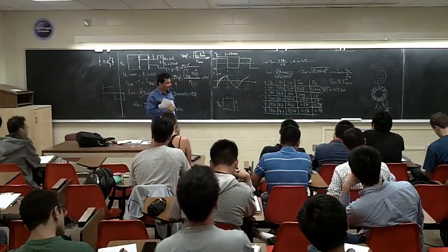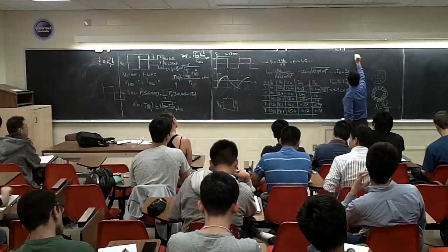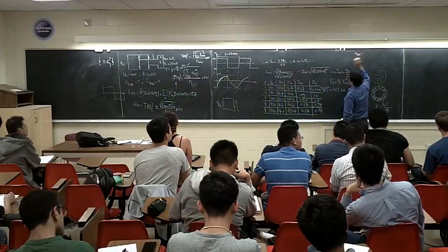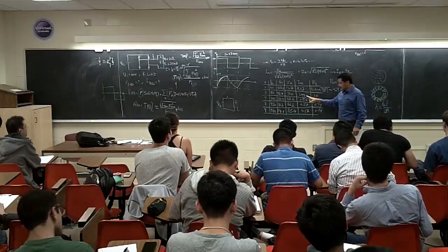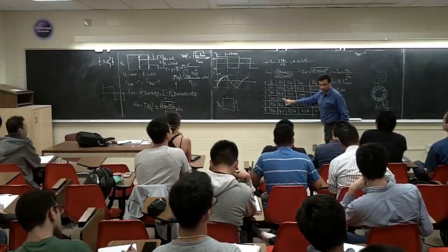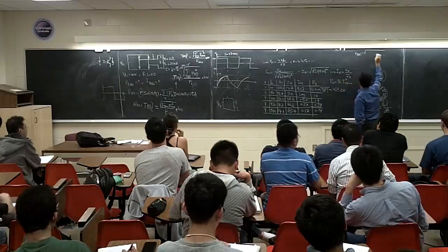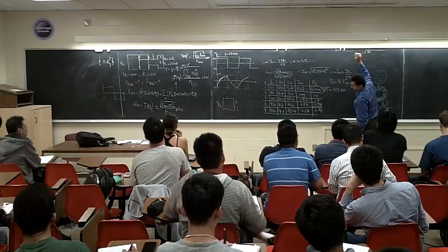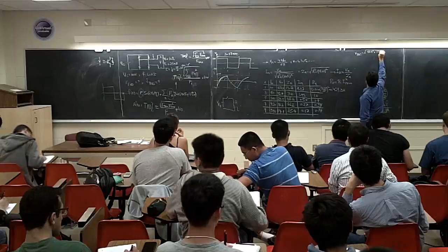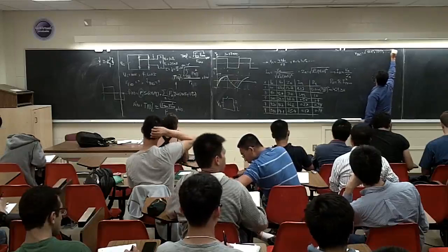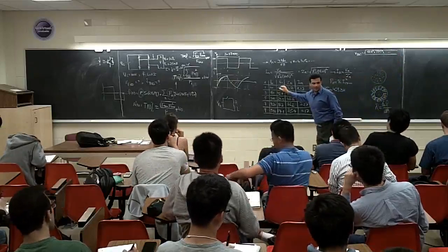Right. Now we want to calculate the THD of the voltage and current. So, how much is the voltage THD? Based on that equation I put over there, it's going to be the square root of the sum. Let's go, where is the voltage here? It's going to be this one to the power of 2, plus this one to the power of 2, plus this one, right? So it's going to be 42.4 to the power of 2, plus 25.5 to the power of 2, go all the way, divided by, how much? I use the maximum values, right?